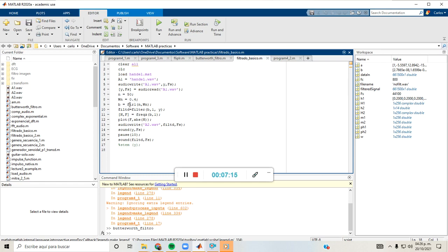And then we will use this filter here, which is going to be stored in variable B, and we again use the filter function we used when I showed you the Butterworth filter, and we are going to filter the input signal here. We want to see also the magnitude response, and we want to see it graphically. And after that, we will use the filtered version also to save it into a WAV file